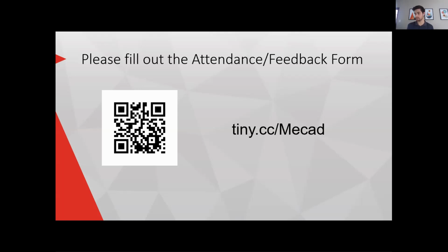So if you want to do actual circuitry simulation, you're going to use something like KiCad or some other ECAD type product for that. SolidWorks doesn't include that. You do get CircuitWorks, but CircuitWorks is just a way to add circuit boards and their components into your 3D models. So they won't be functional. They'll just be for fitment and maybe for thermal testing. So you can do thermal simulation of those components. If you want to do the actual circuitry testing, you will have to use something like KiCad or another ECAD. Yeah, like Octave or something like that.